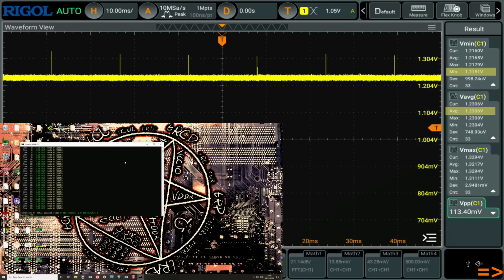The thing is, the voltage regulator on this board goes in 5 millivolt steps, so I can't really do anything about this, right? If I reduce the voltage by another 5 millivolts, we'd be looking at 1.225 instead of 1.23. Anyway, if I don't touch the mouse, everything looks very good. If I do touch the mouse, things still look pretty damn good. Like, we're no longer seeing undershoot below 1.2 volts. Compared to the solid fat yellow line that we have right now, we can obviously see that if I move the mouse, there are some spikes downwards.